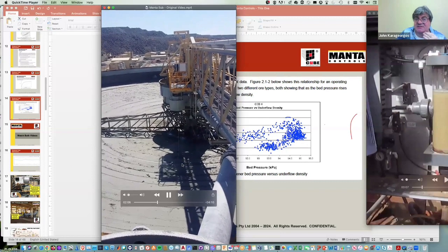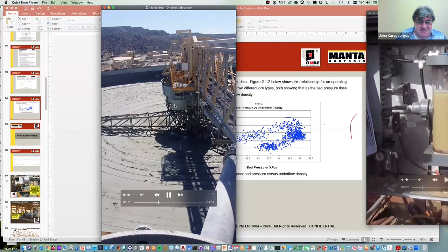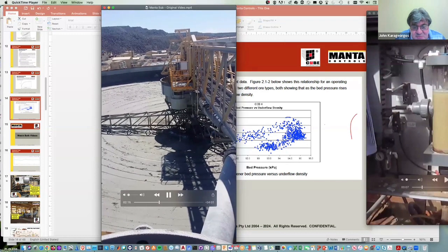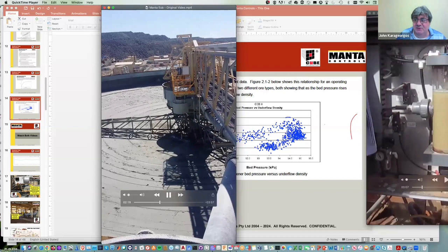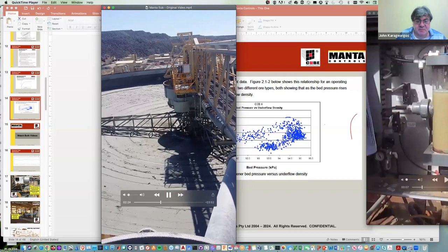And that's one set of readings. It'll come up, give itself a good wash. You'll see the sprays turn on. You can see here, this is a submersible ultrasonic. They're a good idea if you're on a fishing boat fishing with seawater and sand, but not in a thickener. We haven't had those working properly ever.